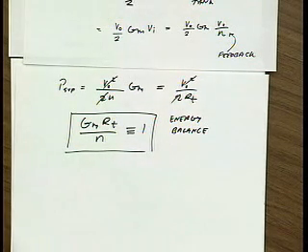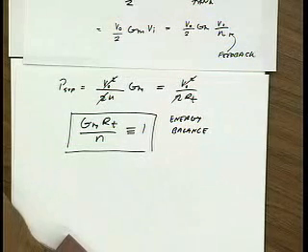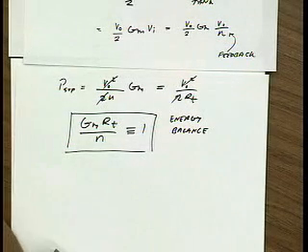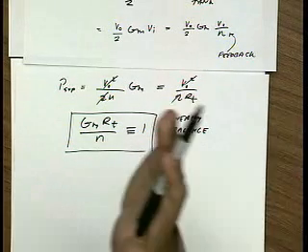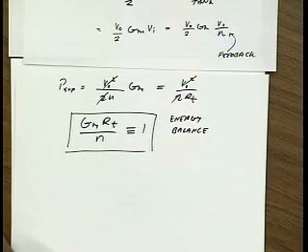So we'll go back to that linear circuit perspective just to gain some intuition. Just quickly to answer your question, the reason the poles move is because as the amplitude grows, the GM of the circuit goes down. And that means the loop gain goes down. And as the loop gain goes down, the poles tend to move back into the left half plane.